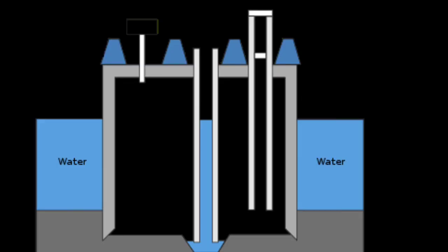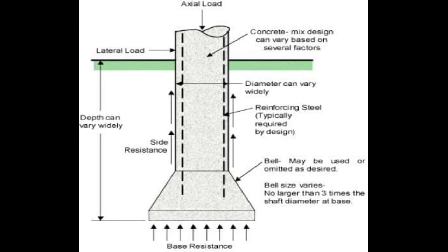This is the second type of deep foundation, drill shaft. Drill shaft is also called caissons, drilled piles, cast-in-drilled piles, or cast-in-situ piles. A borehole is drilled into the ground. The concrete is placed into the borehole to form the pile. Rotary boring techniques allow larger diameter piles than any other piling method and permit pile construction through particularly dense or hard strata. Construction methods depend on the geology of the site.